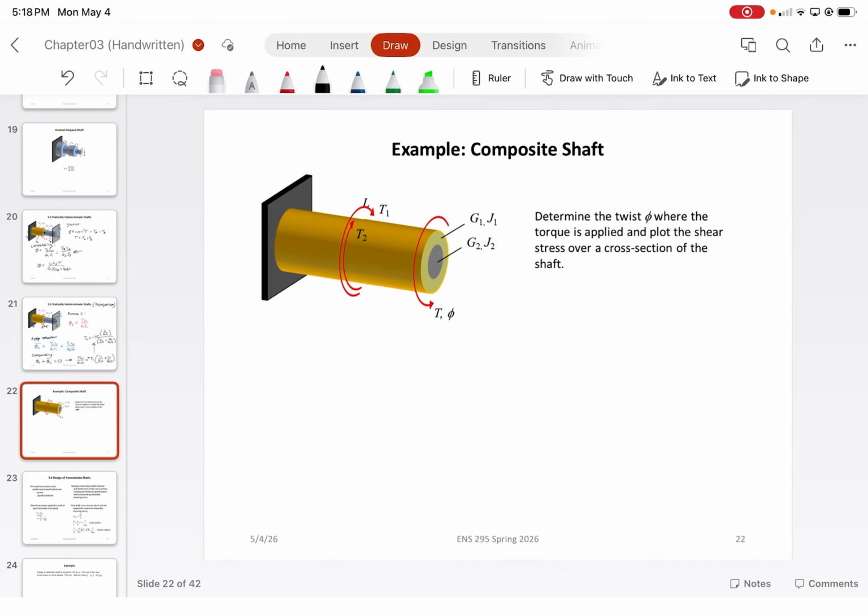What? You have to find n? What do you mean n? Like the modular ratio? Is that what you're asking? I wouldn't say it's necessarily needed. The only time it's really needed is when you have beams because it just simplifies the process, but that's just an additional term to help clarify things. So, what was the one rule that was applied to all composites in being able to solve for everything? Was it the strain? Yeah, shared. The strains are shared. All right.